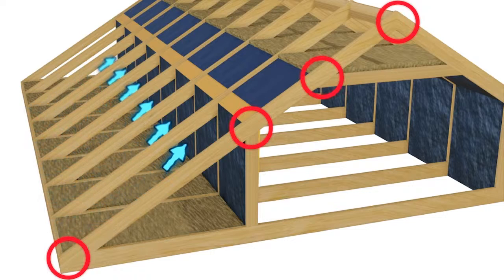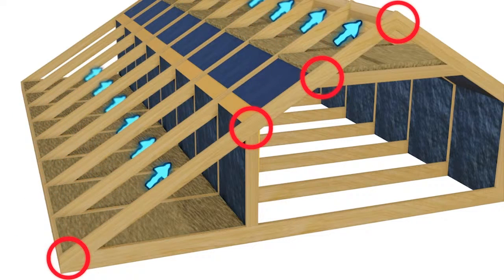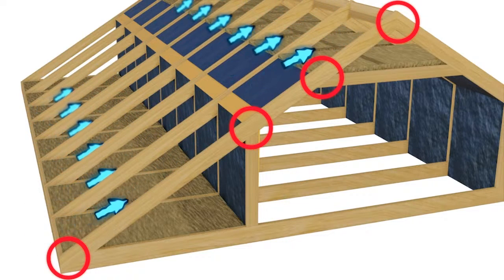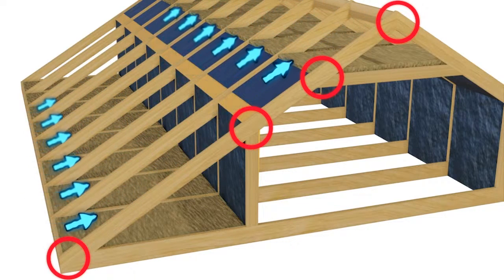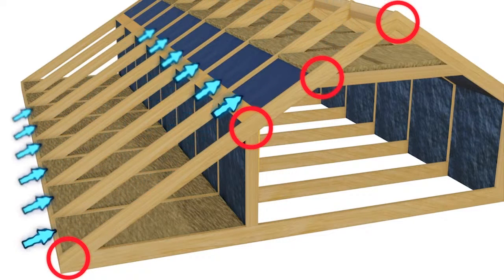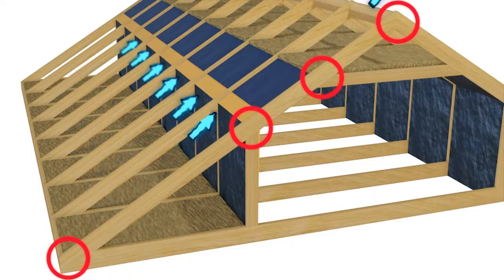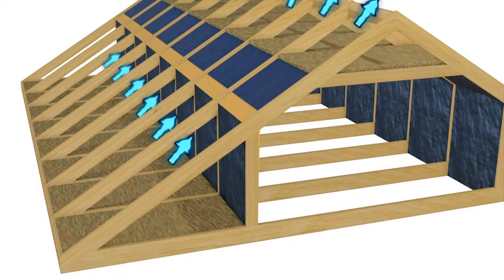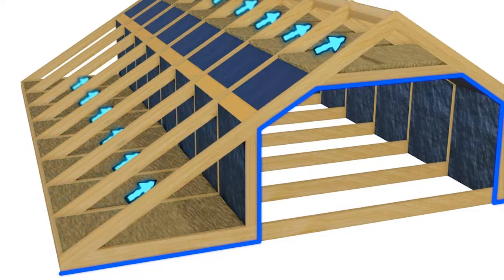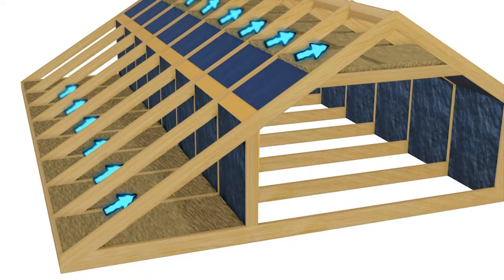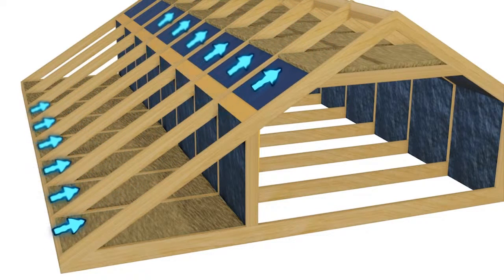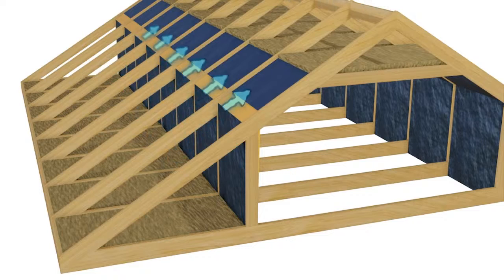If, for example, the roof voids require ventilation, then additional mid-level vent openings may be required at the top and bottom of the inclined sections. This might be the case even if airflow can be provided through the combed section, as it may be difficult to design in dependable air movement under all weather conditions. Achieving a reliable convection-tight air and vapour control layer can also be difficult in this type of construction, as not only must service runs be sealed, but the actual junctions between the vertical, inclined and horizontal structures must be addressed.